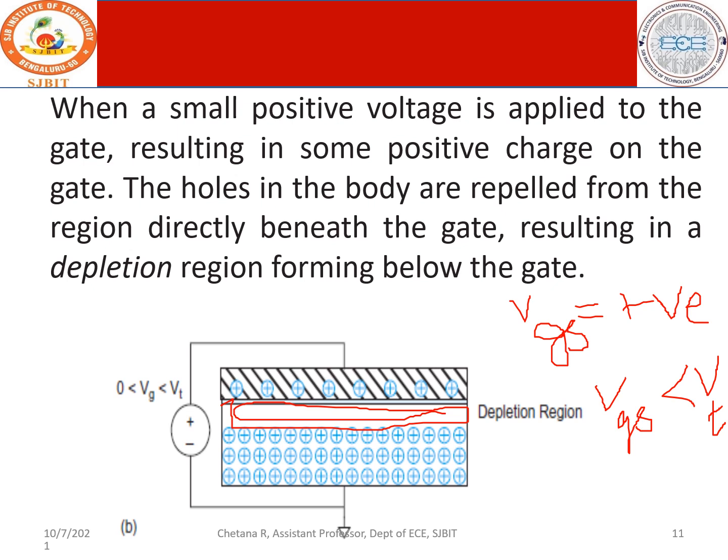What is the threshold voltage? The threshold voltage for NMOS is given as a standard. We have to follow the standards as per the design. It is given as 0.2 VDD, irrespective of the drain supply voltage. If you have 5 volts, 5 into 0.2 is equal to 1 volt. So you have to give the voltage such that the gate voltage is less than 1 volt.